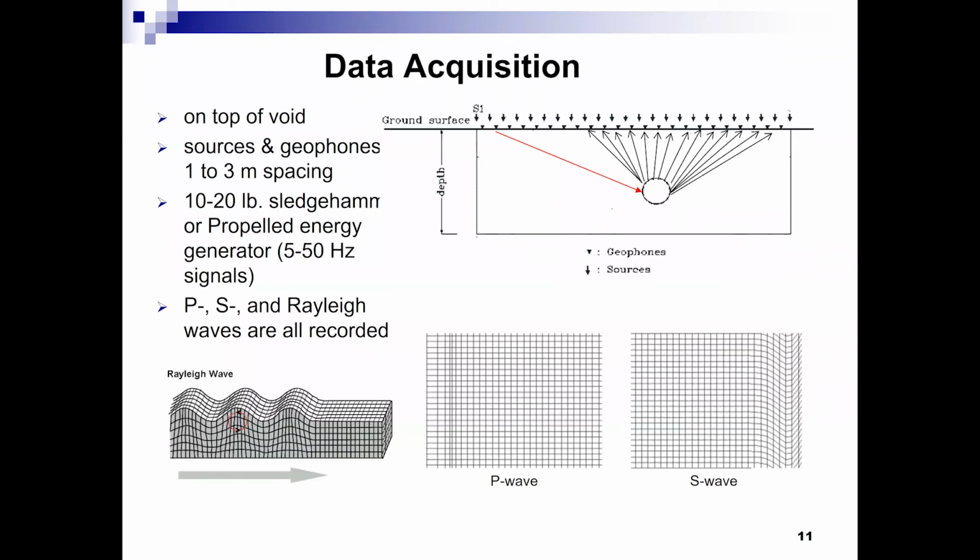Yeah, it's difficult to measure high frequency components on the ground surface because they are still dominated by the Rayleigh wave. So it's still stuck with the Rayleigh wave. You cannot separate them in the time domain. True. So they are mixed together at geotechnical scales. That's why our scale is more difficult than large scale. We don't have a problem with the computer, but we have a problem with the Rayleigh wave. So we cannot separate them.